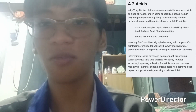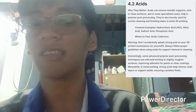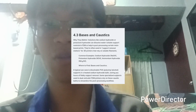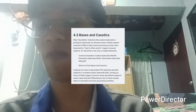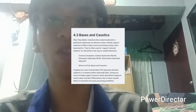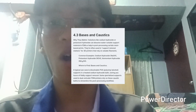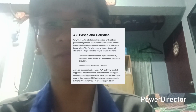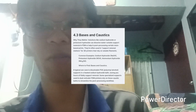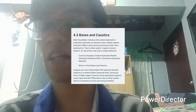They're also heavily used for certain cleaning and finishing steps in metal 3D printing that will be discussed later. Number 3, bases and caustics. These include solutions like sodium hydroxide or potassium hydroxide that can dissolve water-soluble support materials in fused deposition modeling, which will be discussed later on during that part, and helps in post-processing certain resin-based prints. They're often used in support removal stations for 3D printers that rely on soluble filaments.